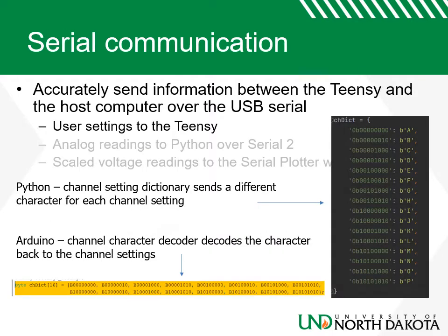For serial communication, to get the user settings from the Python GUI to the Teensy, the Python PySerial communicates very well in single characters. So rather than sending the channel settings in an 8-bit stream, I created a dictionary to match a specific letter to each possible channel setting, and then have that be a single character to send over to Arduino. And then on the Arduino, the single character gets decoded back into the channel setting.